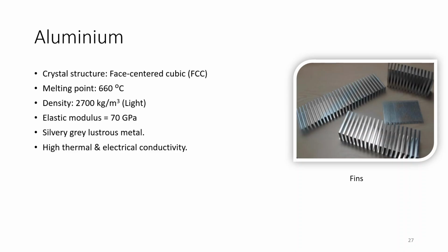The slip plane is the densest plane, and the direction in which you have the highest number of atoms will be your slip direction, and the plane which has the highest amount of atoms will be your slip plane. Okay, ma'am. So the combination of those will be the slip systems. I think we'll talk about that in coming chapters as well, or if not, I'll add a slide in the next chapter.